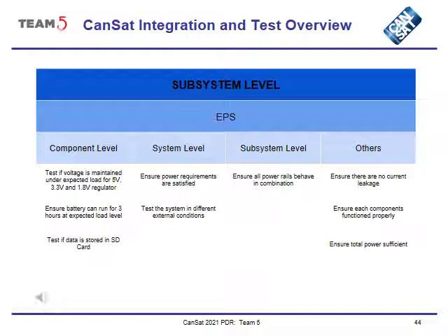Test the system in different external conditions. Subsystem level, ensure all power rails behave in combination. And others, ensure there are no current leakage, ensure each component functions properly, and ensure total power is sufficient.